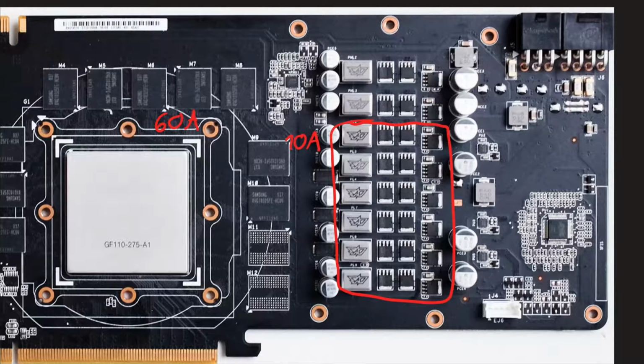And you will see that the low side MOSFETs are rated for something like 25 amps each, so you could basically handle 50 amps per phase,